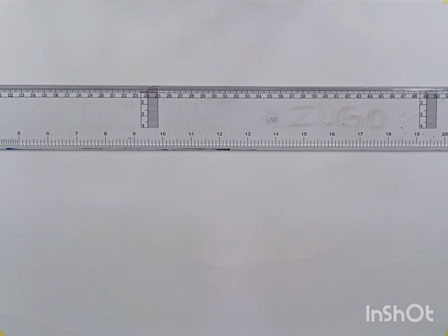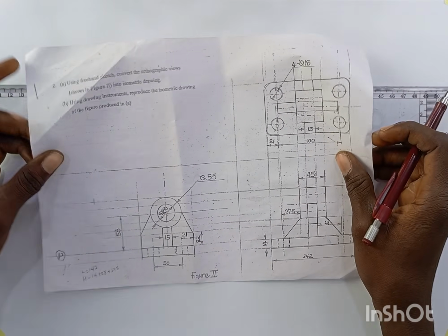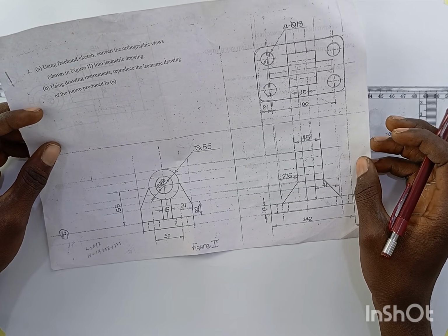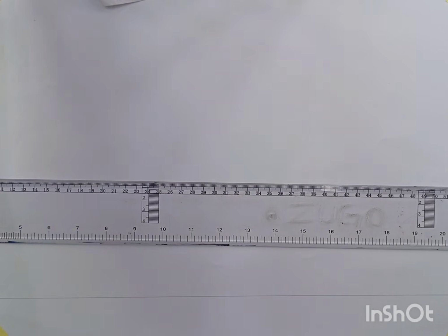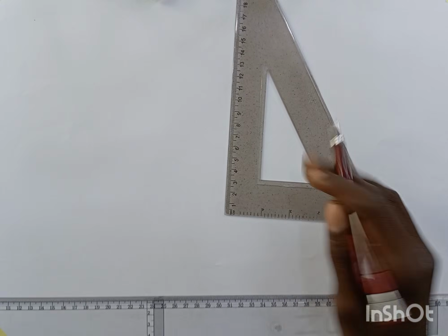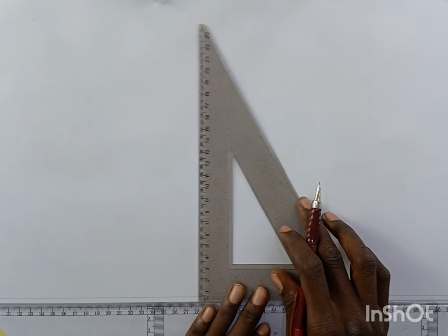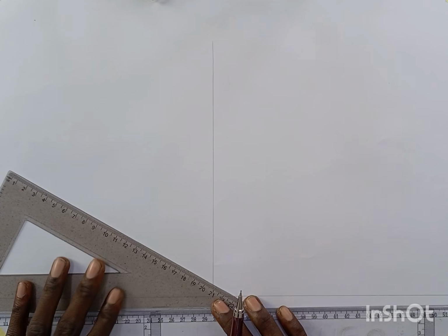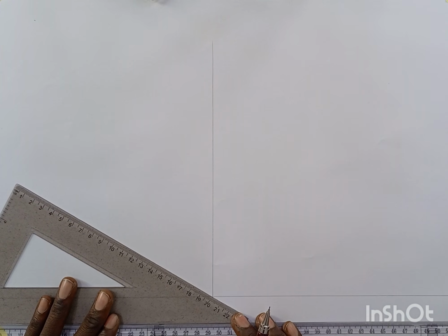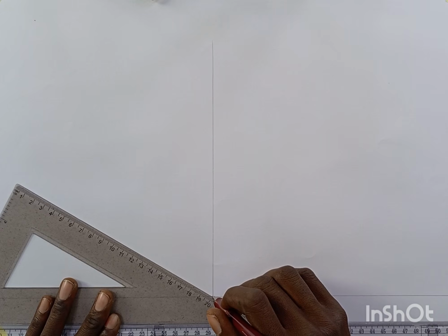In this video, we are going to discuss the second isometric drawing from the problems we have here. As you all know, in isometric, we first draw our plane, that is the x-plane, and then we make our perpendicular line, or the 30, 60, 30, 90 degrees we have. So this is my 90 degrees, like this, and then the 60 degrees can be drawn like this. Or you can use a compass to draw the 60 degrees. Okay, here it is. So, like always, I'm going to be making my lines